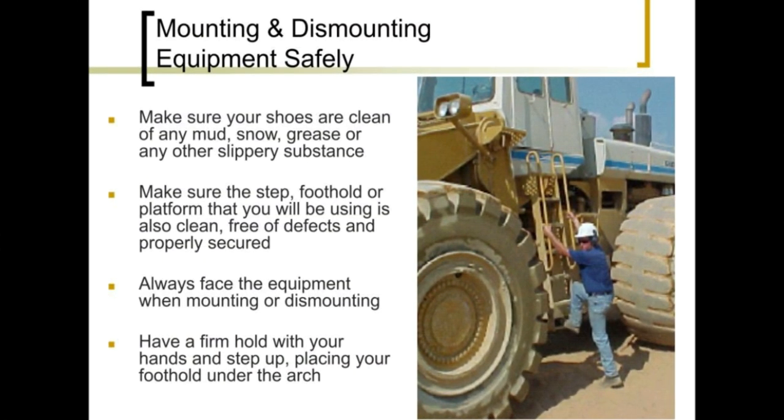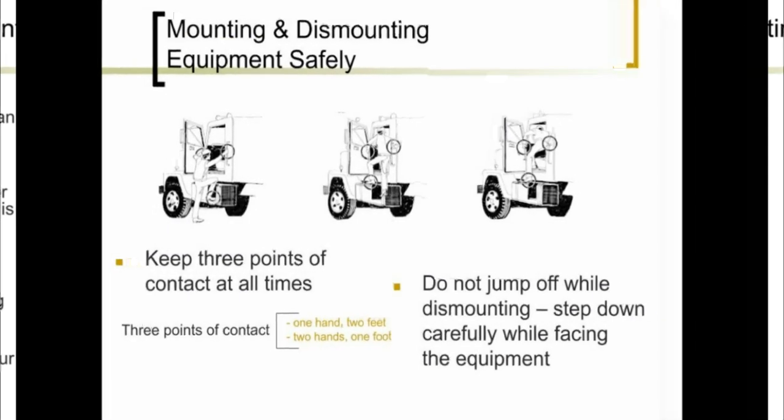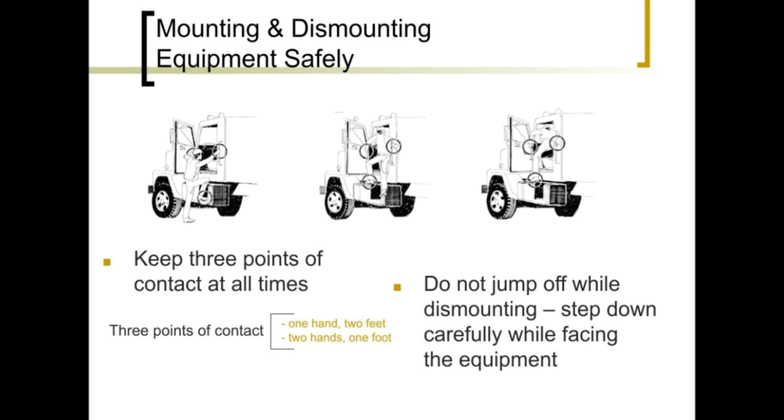Mounting and dismounting equipment safely. Make sure your shoes are clean of any mud, snow, grease, or any other slippery substance. Make sure the step, foothold, or platform you will be using is also clean, free of defects, and properly secured. Always face the equipment when mounting or dismounting. Have a firm hold with your hand and step up, placing your foot under the arch. Here's some examples of mounting and dismounting a truck.